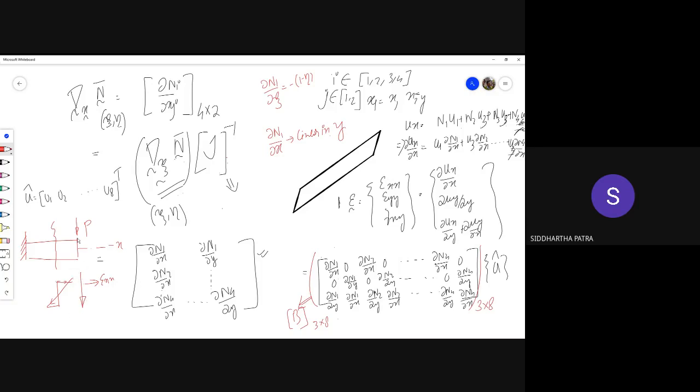And in which direction is it changing most rapidly? Obviously the bending moment would be changing along the axis, and the bending stress and hence the strain would also be changing along the axis. But in the y direction, it is going from high positive to high negative. So the maximum variation is along the y direction.